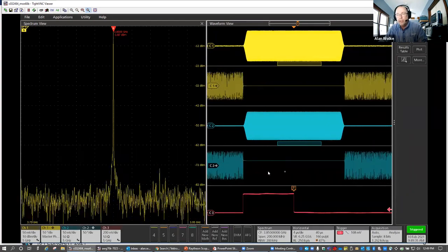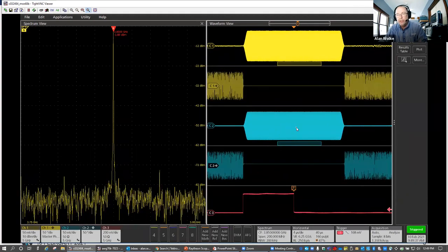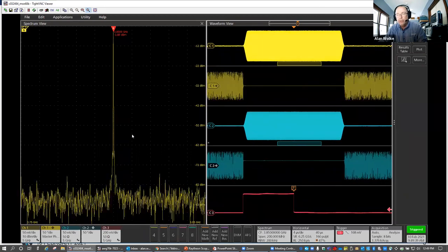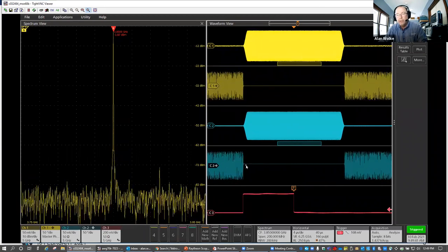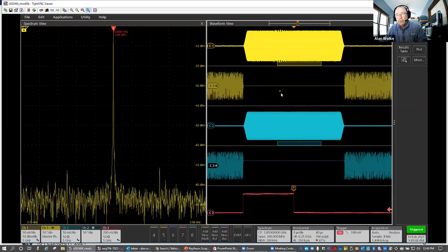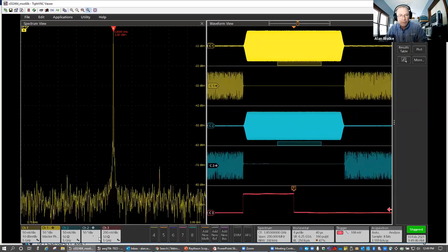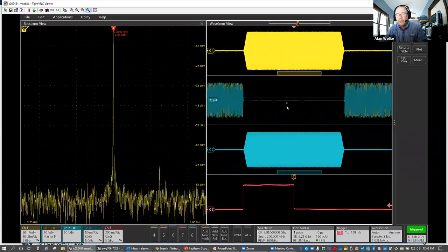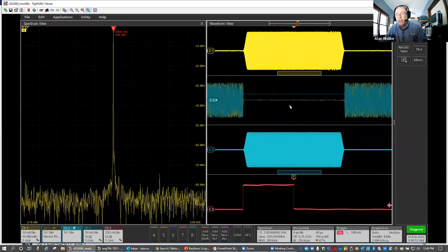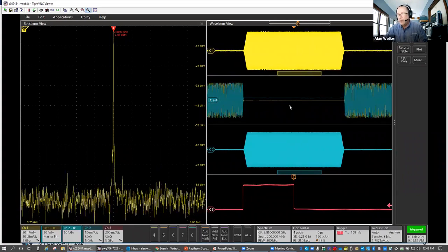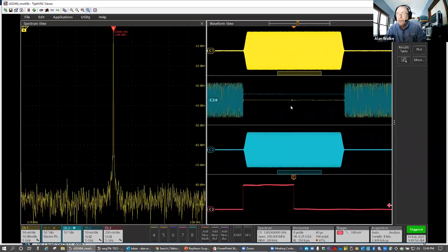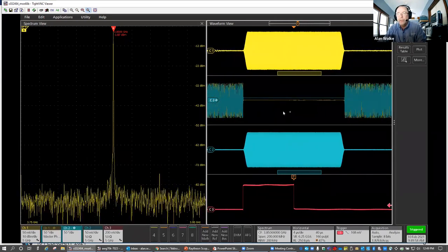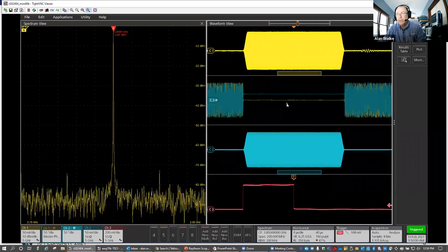Okay, so we can actually see now here on channel 2, here's that same pulse. I don't have the spectrum of that one turned on right now, but then I can look at the phase of channel 2 with respect to channel 1. In fact, if I lay those on top of each other, it might be easier to see that as well. You can actually see the phase difference between those two channels. So if you're doing any kind of electronically steered arrays and you're looking at modulator characteristics and things like that, you'd be able to look at that kind of thing here.